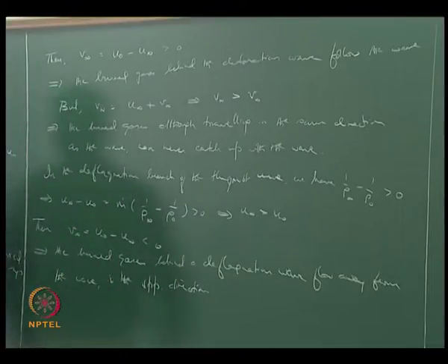Since the gases are going to go away from the wave, we don't have to worry about what their speed is relative to the wave speed, because they are never going to catch up. So let's not do the extra thing that we did for the detonation. We don't have to worry about whether they are going to catch up or not, they simply go away.